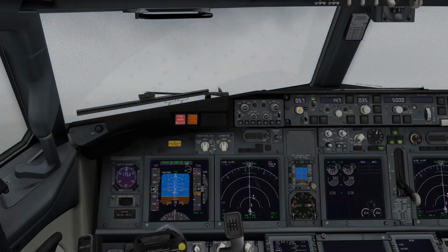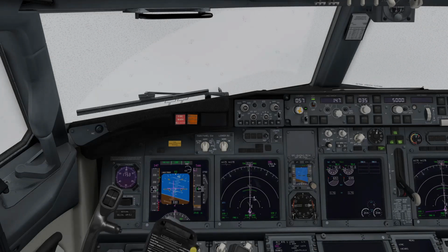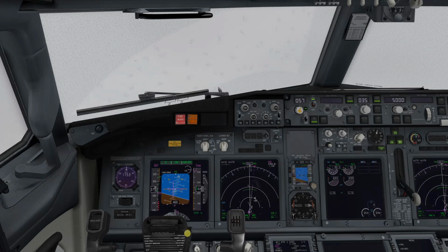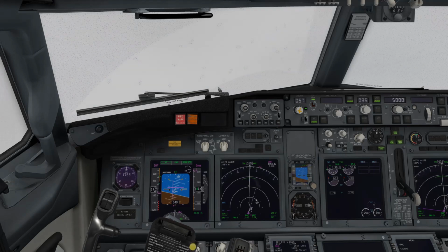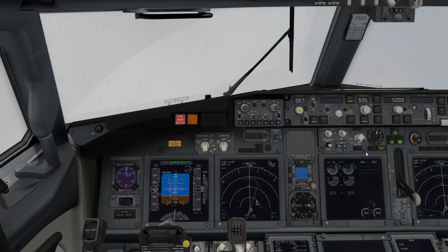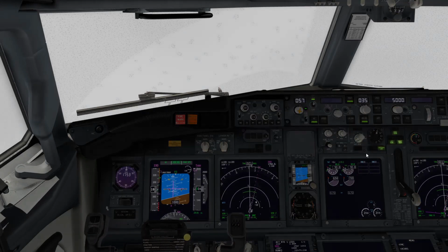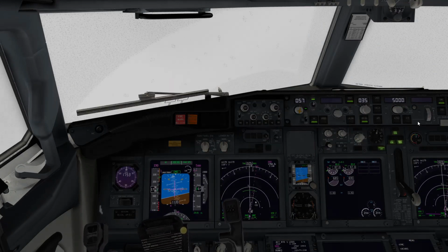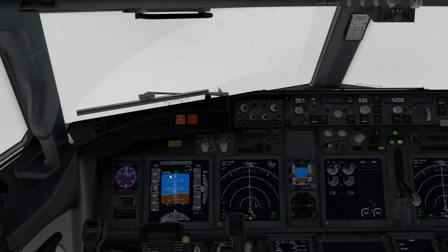Per second for rotation rate. That was a little bit slow. LNAV engaged. 400. VNAV speed. Alright, I'm following the flight director here. I'm not sure where it's taking me, so what I'm going to do is go ahead and select what I want to do. 1000. Engage the autopilot in command. So climb thrust is set at 1,000 feet. And there's the command indication that tells us the autopilot is engaged.